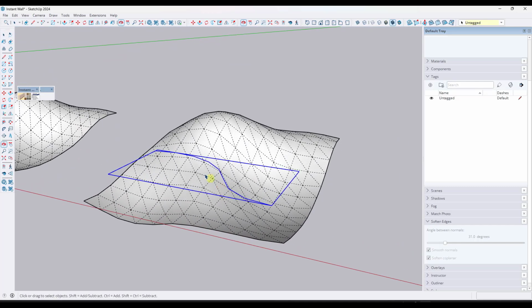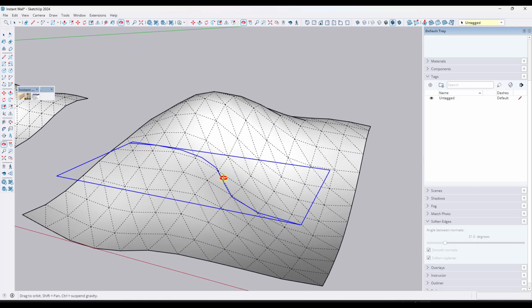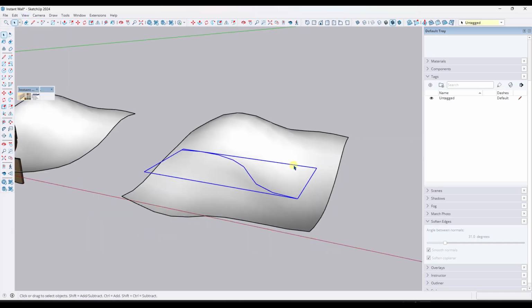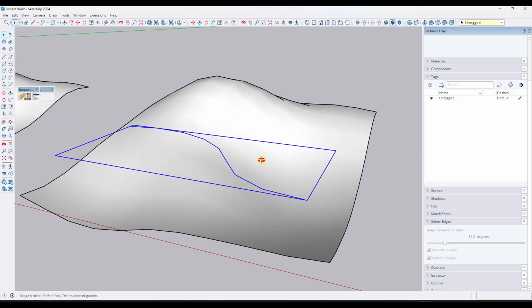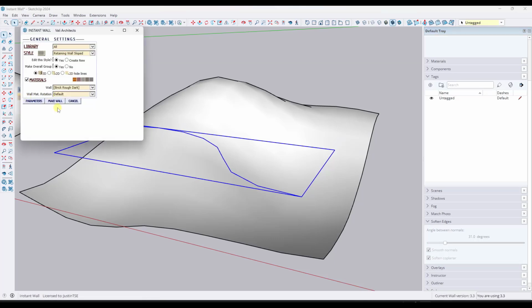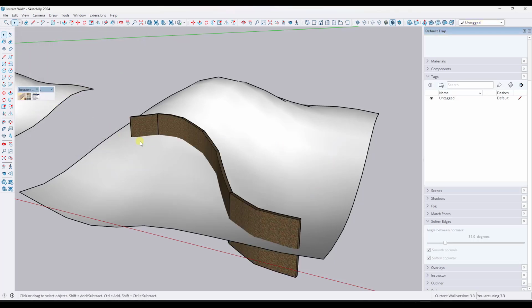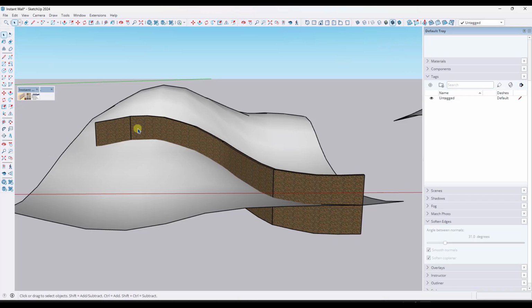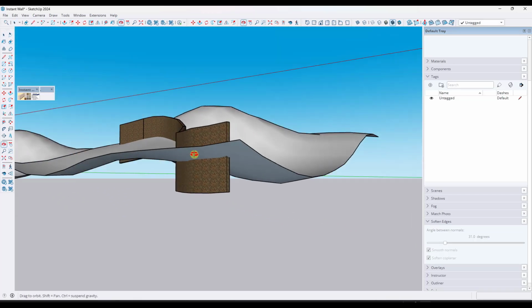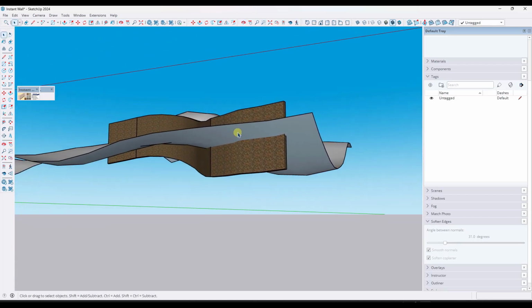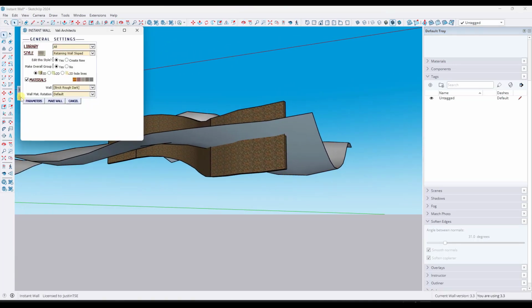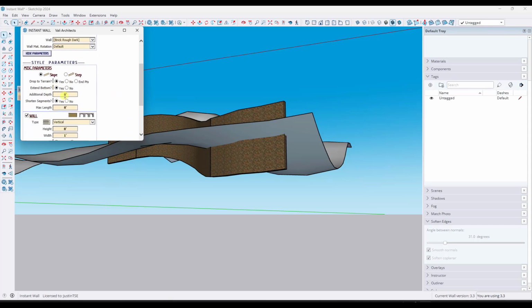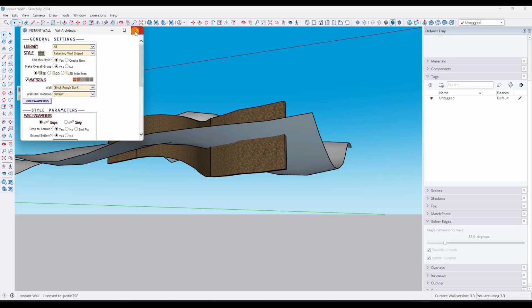And so let's say we did the same thing, but this time I've got an edge that I simplified over here, like this. So same exact curve, I just simplified it into a number of segments in here. So if we look at the way that this retaining wall drops to terrain right here, notice how I have fewer breaks in that object. So it's still dropping it to the terrain, but it's kind of following along here like this. And then notice how it's also extending this down below because we set the option for extend bottom to be 8 feet right here. Now you could set this to shorten the segments in here. I don't necessarily do a ton of that, but you definitely could.